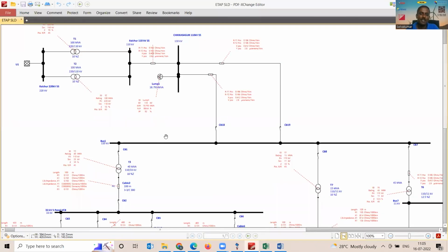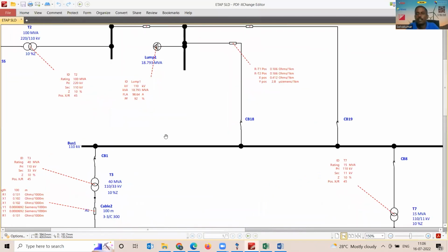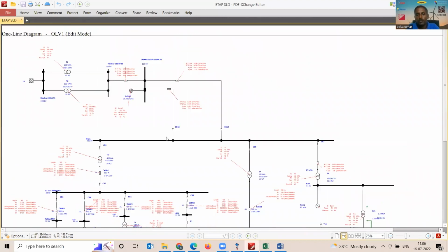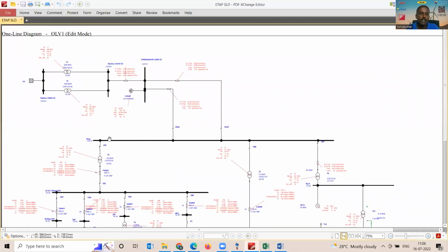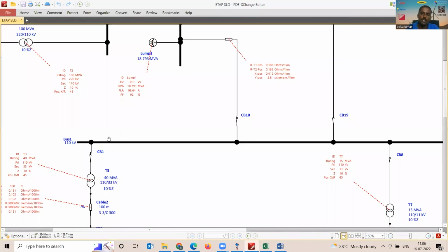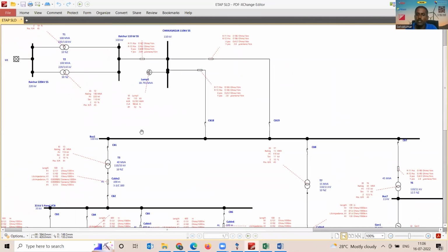Double bus bar scheme is missing in the ETAP model, and that's the objective of load flow. Whether it is a single bus bar with a section, main and transfer, or two main or 1.5 breaker scheme, all are immaterial for a load flow analysis.